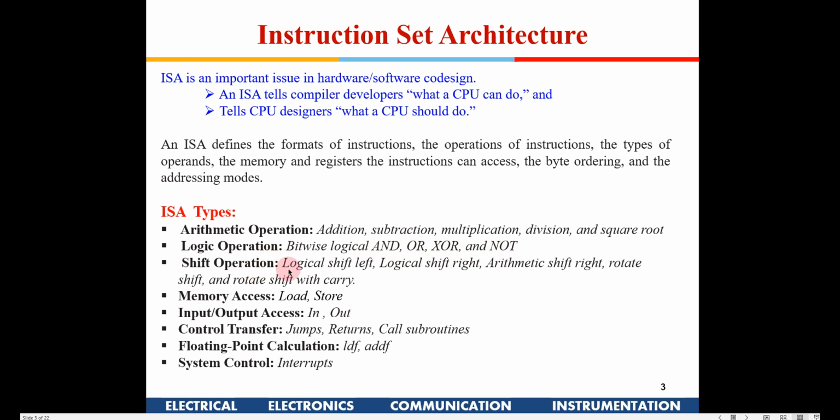Similarly you could have shift operations, right? There are two kinds of shift. One is known as logical shift, and the other one is known as arithmetic shift. Okay, in the logical shift left, the entire data will be shifted towards the left. You can specify by how many bits you need to shift left. If I say shift left by 1 bit, then the MSB will be thrown away, and from the LSB side a 0 will be pushed in. Okay, that is known as the logical shift left.